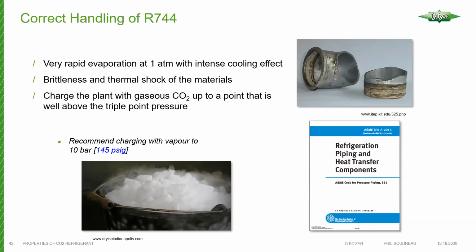Another thing to consider with CO2 is its very low temperature when exposed to low pressures. It has a very rapid evaporation at 1 atmosphere with very intense cooling effect. And generally, steels and things like that have a fairly high pressure capability, which is a reason why stainless steel is used on the high side of CO2 systems that operate transcritically. But copper has a very good lower temperature limit.